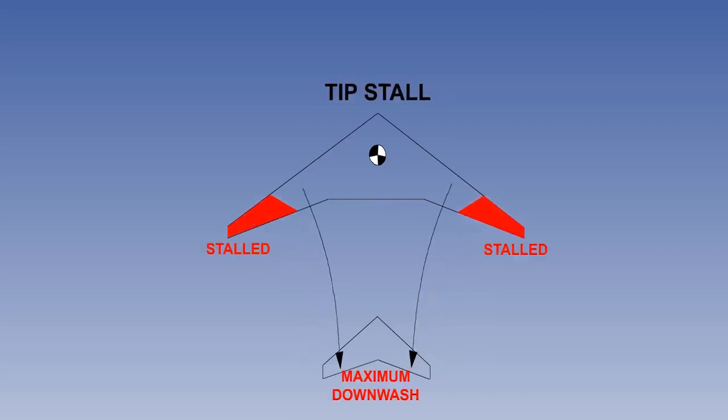As soon as a swept wing begins to stall, both the forward CP movement and the increased downwash at the tailplane cause the nose to rise rapidly, further increasing the angle of attack. This is obviously undesirable and unacceptable behaviour at the stall, and can result in a complete loss of control in pitch from which it may be very difficult, if not impossible, to recover. This phenomenon is known as pitch up, and is a very dangerous characteristic of some high-speed swept-wing aircraft.